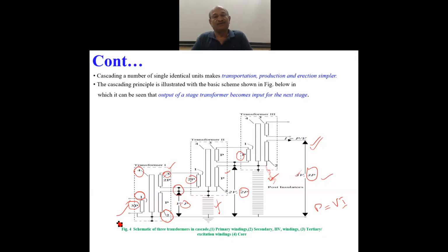So the conductor cross-sectional area in all the 3 can remain the same, in spite of the reduction in the current being carried by the third stage, and in spite of the current carried in the first stage being higher. But the insulation ratio, the transformation voltage ratio, is the same. So the insulation provided in the 3 stages remains the same. Get the point?